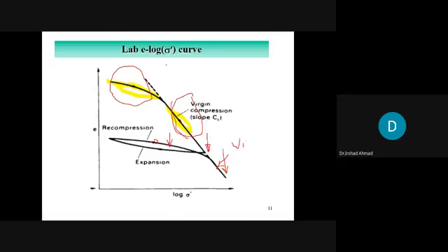So it would be somewhere here between the linear part and the compression part. This is called the pre-consolidation pressure. And this is the beauty of the clay and silt material, that it keeps its stress history. It remembers stress history.